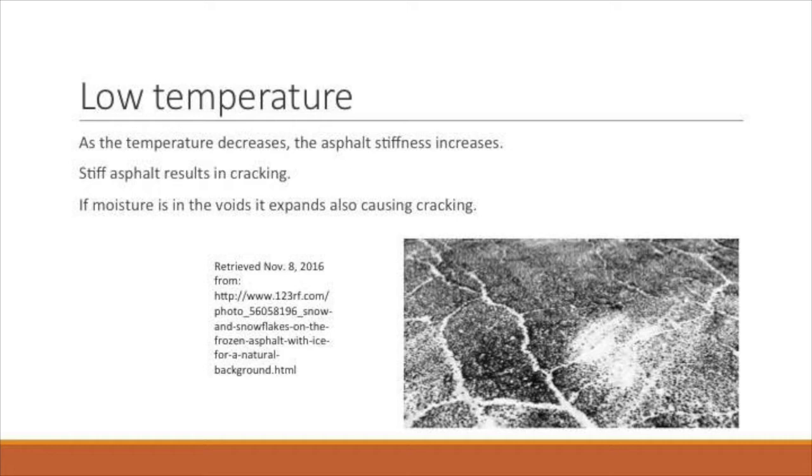The result of this is cracking in the pavement, as there is less give and less flexibility. Also, if there is moisture present in the voids, expansion occurs when it freezes. This expansion can also cause cracking in the asphalt.